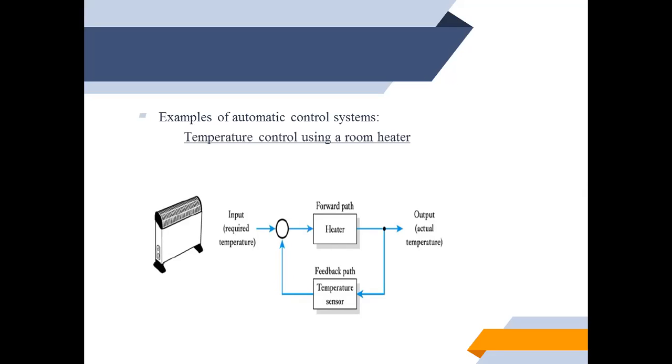That is the thermostat. Once the 22 degrees Celsius temperature is attained, the thermostat will be cut out. Whenever the thermostat cuts out, the controller will command the heater to stop, and the heating will stop for a certain time.